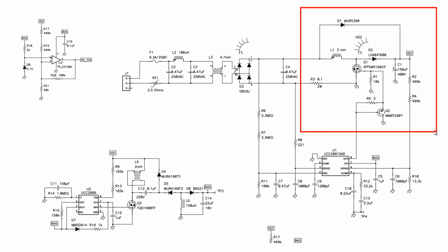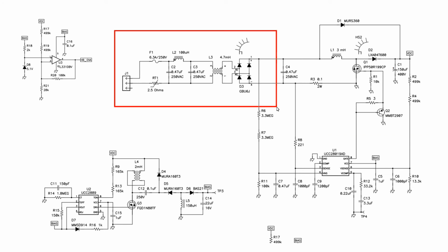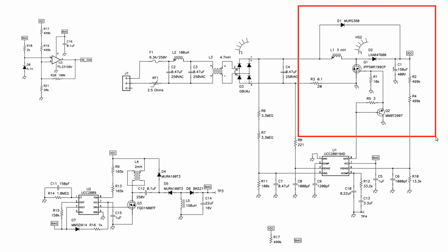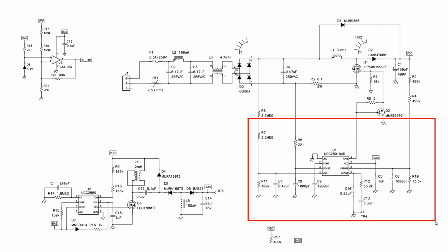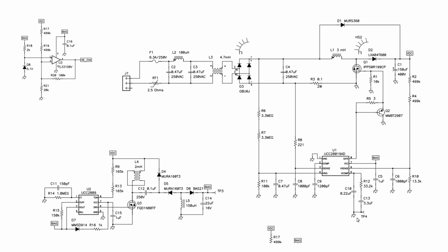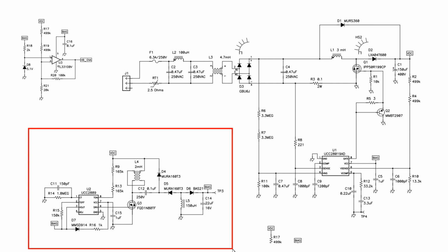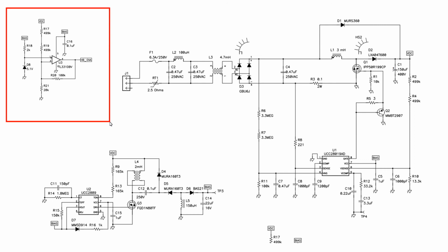The basic principle is based on the inductor and voltage multiplier, raising incoming rectified mains to a fixed voltage value, typically 390 volts. Such a schematic works in a large input voltage range, like from 85 volts to 250 volts. These are the main building blocks: input filter to filter switching noise back to mains, voltage multiplier, and PFC driver chipset. What else do we have? There is a flyback low power switching mode power supply for standby and services voltage, and some schematics for automation purposes.